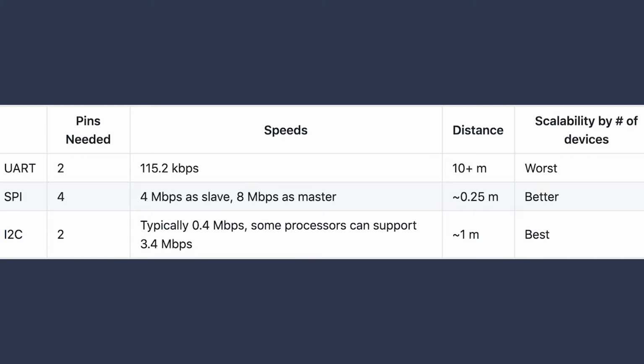In this video, we'll discuss the SPI protocol and demonstrate reading registers from a typical SPI-based sensor. SPI stands for Serial Peripheral Interface. It is a synchronous serial communication interface, which just means that we use a clock to standardize communication and send bits out one after another. SPI is most useful for very high-speed transfers over short distances.